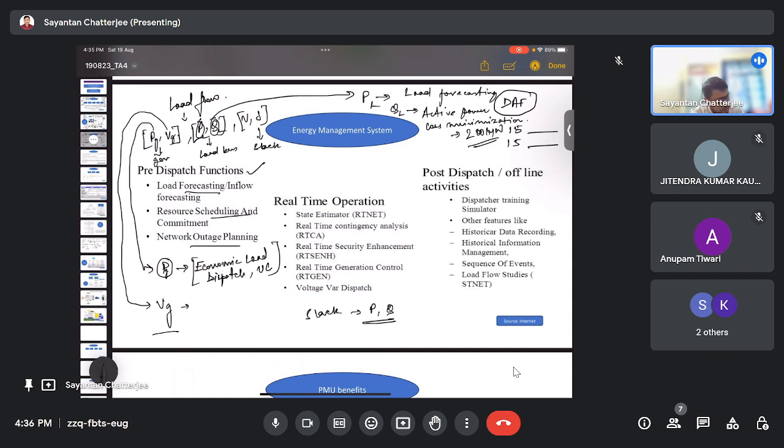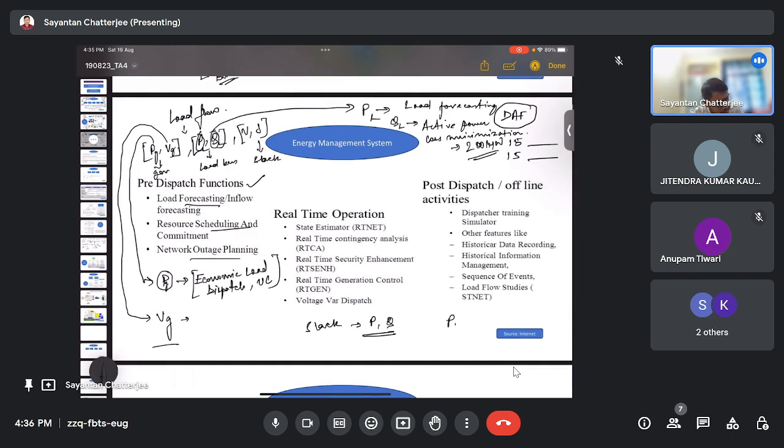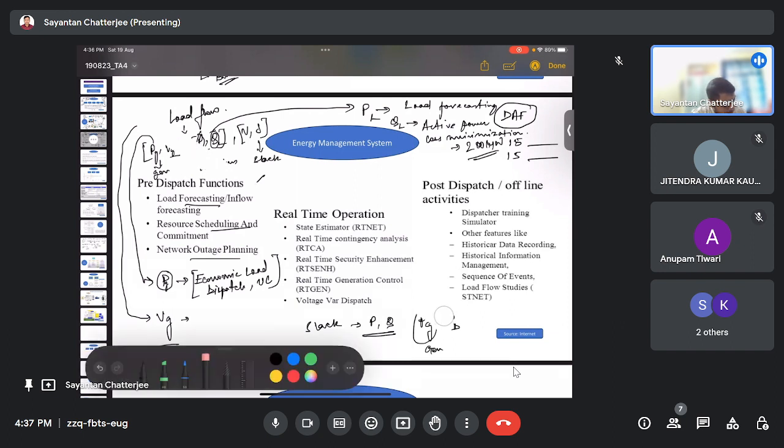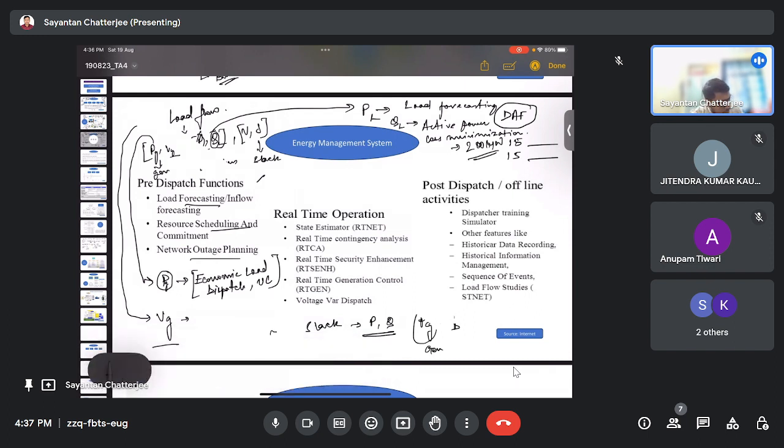Suppose we have a load, PD is the demand and PG is the generation by all the other generator buses. If we don't consider the slack bus, and only consider the PG delivered by the other generators, and PG is lesser than the P demand, then the remaining amount of the demand would be delivered by the slack bus.